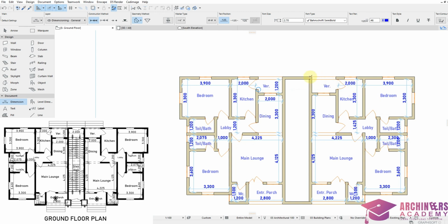For the aspect of a bungalow, we don't need this stair hall. So once we just mirror it, automatically we get what we want. But for this case, which is a storey building, after mirroring we have to drag it to the position where it should be, which is after the stair hall. That is why we must draw the stair hall wall first before we start mirroring, so that we'll know where the other apartment will start from.